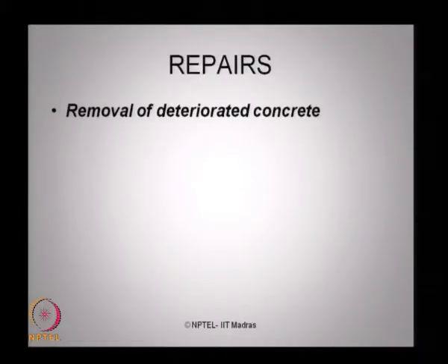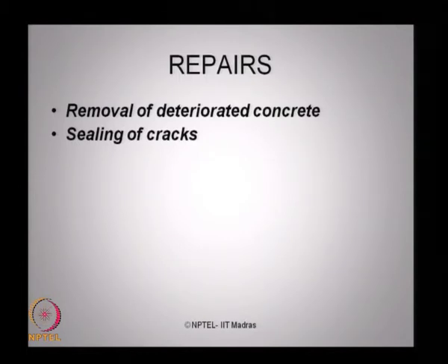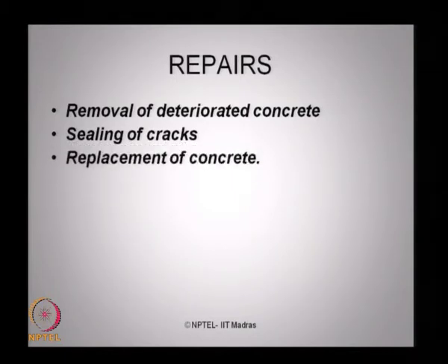If we talk quickly, a brief idea on repairs and repair methodologies of concrete: removal of deteriorated concrete is one of the important suggestions given by researchers, which has been practically used in many marine and coastal structures. Sealing of cracks using different chemical compounds is also being attempted by various engineers in different capacities all over the world to establish a stable performance of concrete members, especially in sea environment. Replacement of concrete is of course a good alternative, but it is as expensive as constructing a new structure. So, the rehabilitation cost of these suggestions can be even higher than the original principal structure.